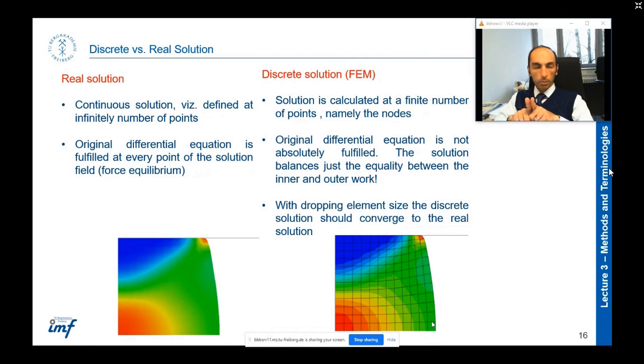Sometimes it becomes so big that you need supercomputers to solve it. So you should see what tools you have for your hardware, and then decide about it. Usually in any simulation, you should study the effect of mesh size on your results. It means that you start from a rough mesh first, and then start to increase the number of elements.